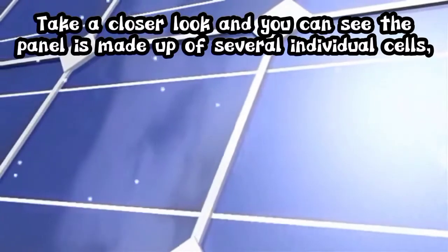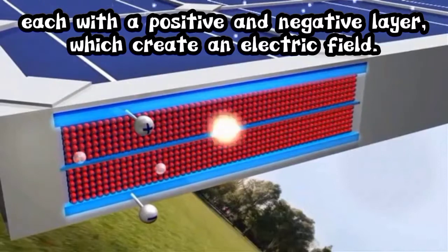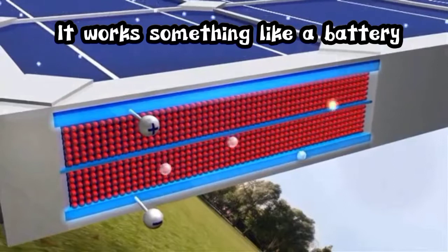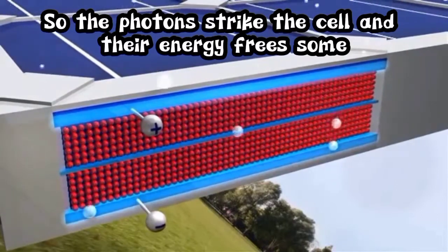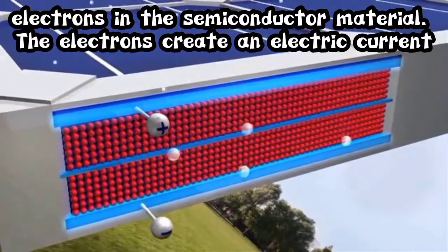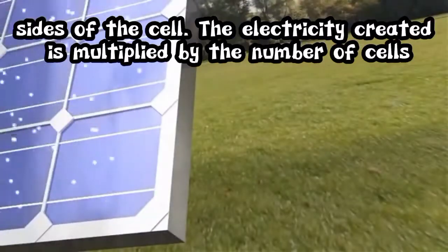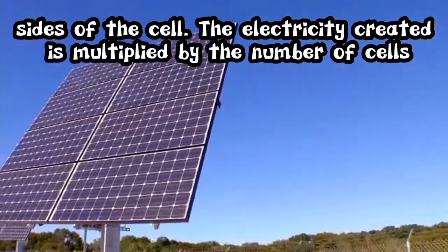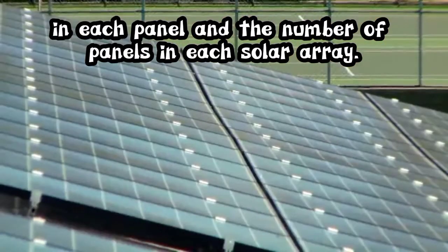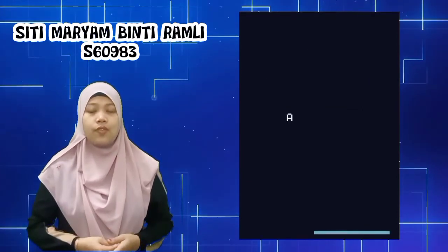Take a closer look and you can see the panel is made up of several individual cells, each with a positive and a negative layer, which create an electric field. It works something like a battery. The photons strike the cell and their energy frees some electrons in the semiconductor material. The electrons create an electric current, which is then harnessed by wire connected to the positive and negative sides of the cell. The electricity created is multiplied by the number of cells in each panel and the number of panels in each solar array.